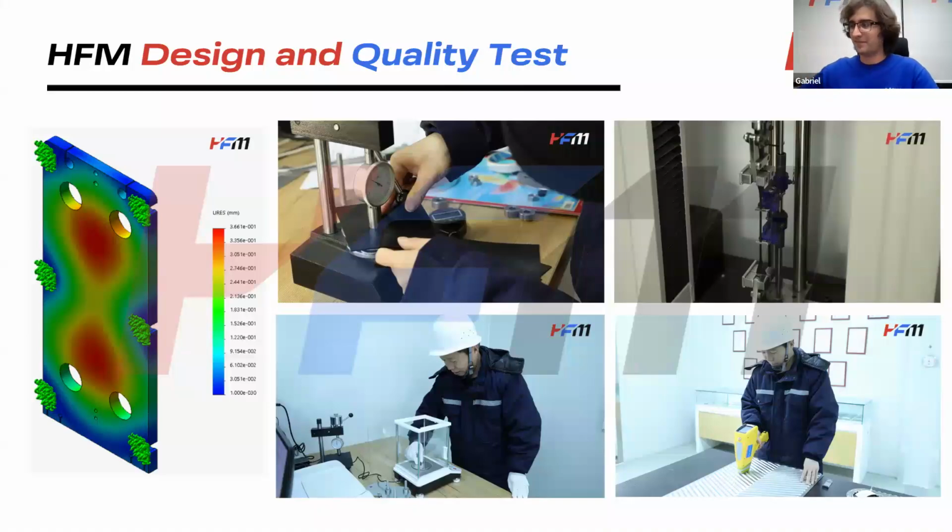And the last picture, where the guy is using an equipment that looks like a gun, is actually a PMI test, because as I said, the plates can be very different materials, such as nickel, steel, and titanium. Well, in the food industry, generally stainless steel. So it also has a kind of purity. For example, 99% of stainless steel, we need to ensure it fits the requirements, and that's what this test does. It tests the purity of the materials of the plates, ensuring that it's going to be appropriate for the requirements we have for the food industry or many other industries as well, as we're going to see very soon.